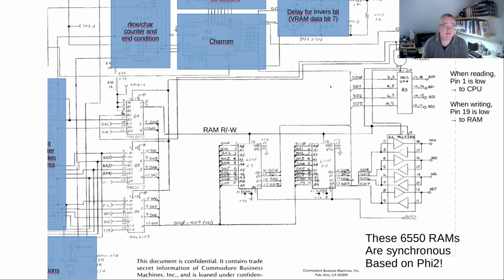So yeah, that looks very strange. Maybe that's a remnant of some discussions they had. As I've seen in later schematics, there's a jumper to move the I/O area to hex 8800 instead of the current E800. Probably they have been discussing that there as well, but yeah, doesn't really make much sense. Could have used read not write.